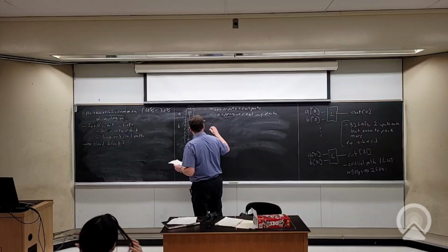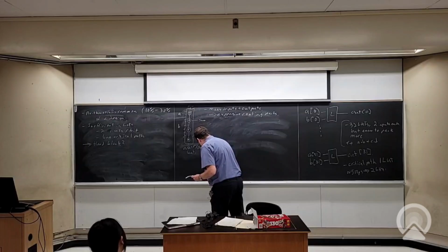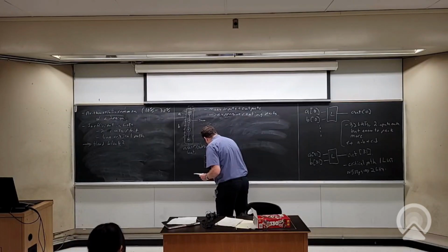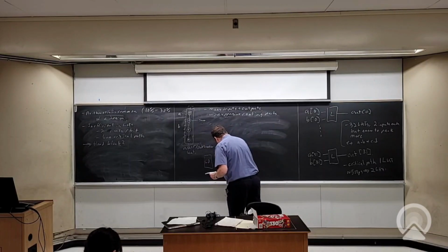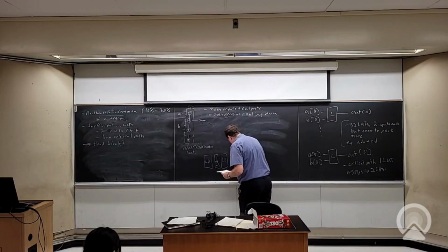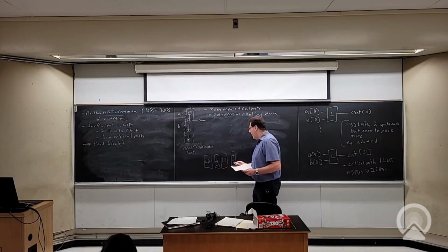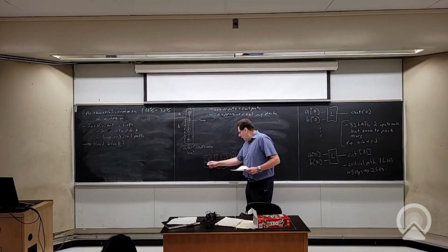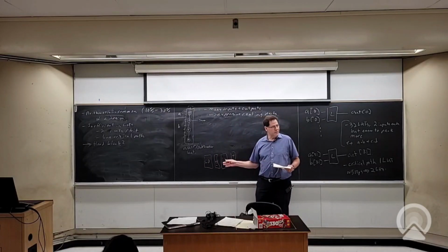There's another thing. If I'm going to make a logic block, and then my adder subtractor, and then a logic block, and then my adder subtractor, or maybe 2 logic blocks, 2 adder subtractors, etc., I'm going to get parts of my design where I only want logic, and other parts where I might have a cascade of adders, like an adder tree.